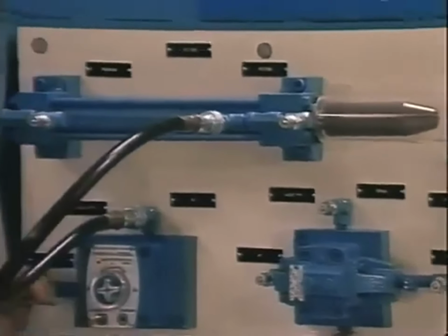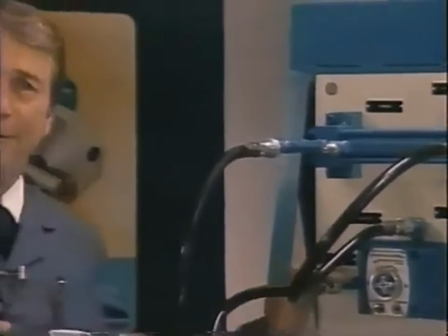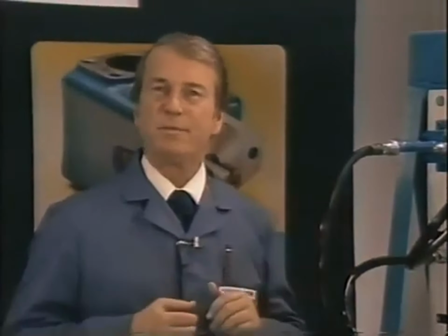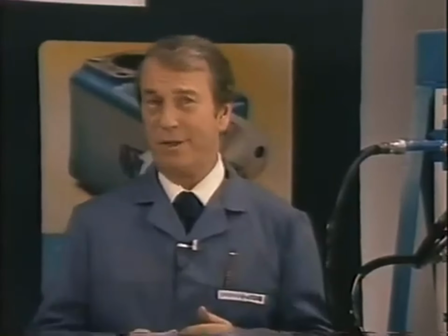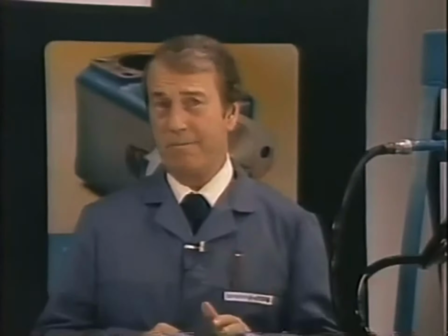Seriously, though, be very careful in removing any hydraulic line. Be sure it doesn't go to a cylinder or motor that's supporting a load. If it does, either lower the load or support it so it can't fall. An accumulator, too, stores oil under pressure even with the machine shut down. If you're unsure about it, find someone who knows before touching a thing.